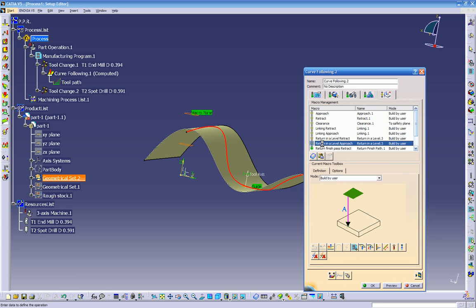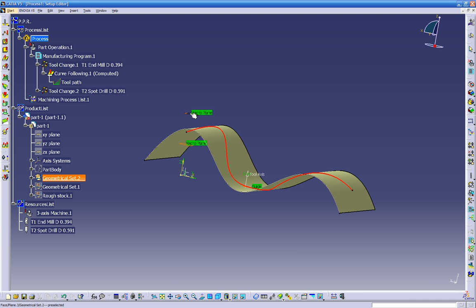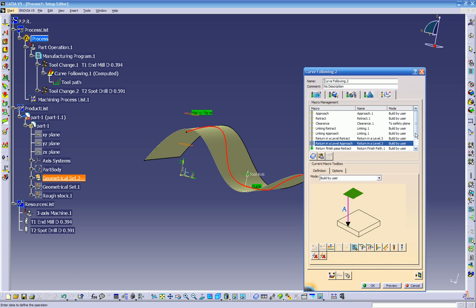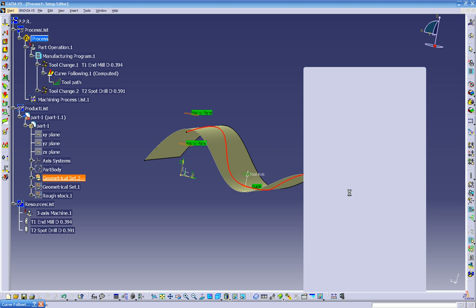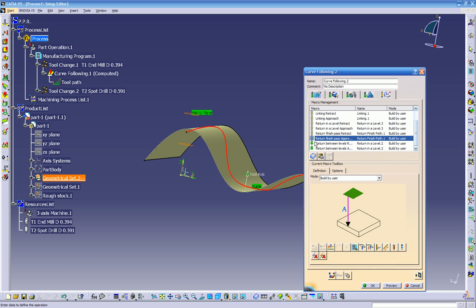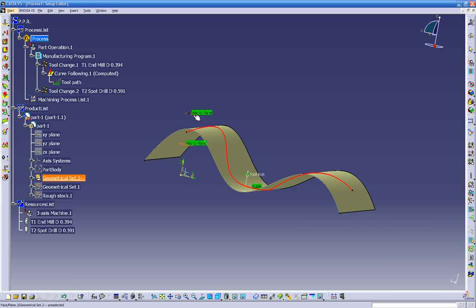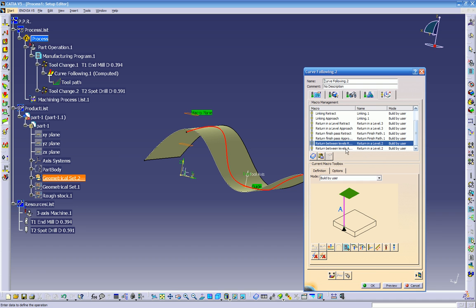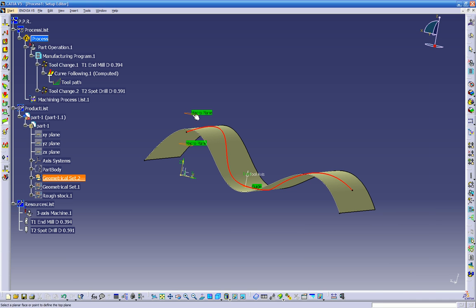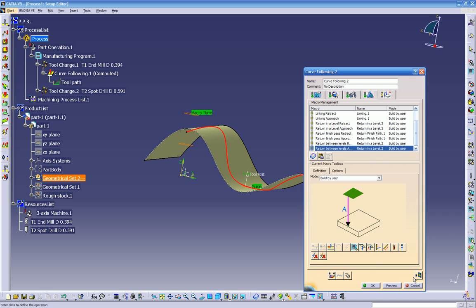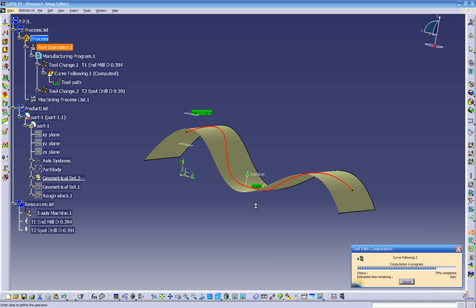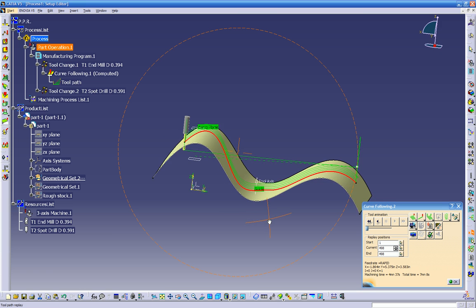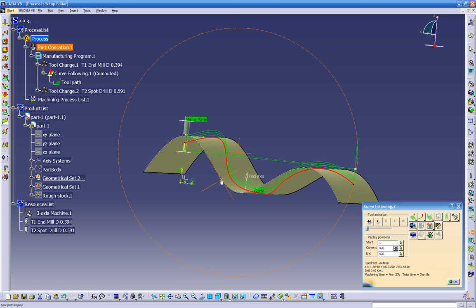The reason I'm going through all this right now is because I want to do a couple passes again. So we want to make sure that we have a nice retract. I know it takes a little bit, but we have to go to each one individually. Okay, once we selected all the planes, let's click on Toolpath Replay. We missed one.